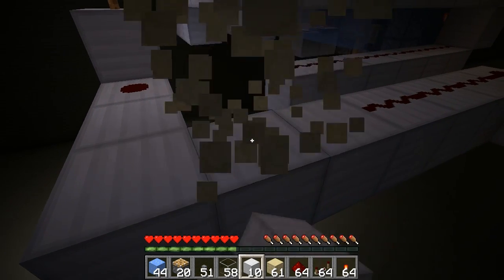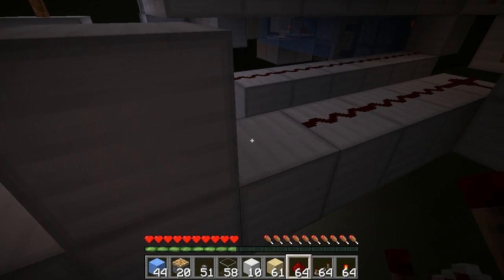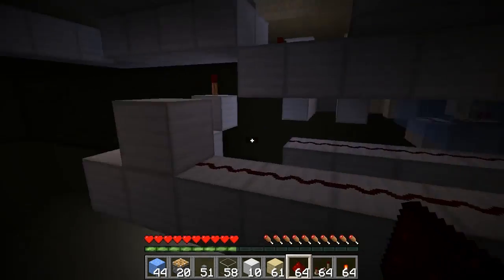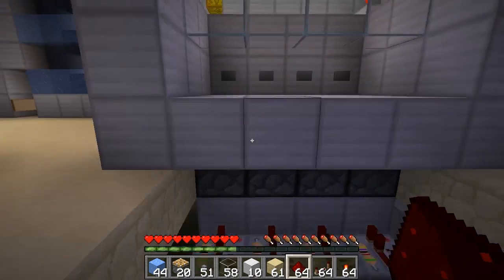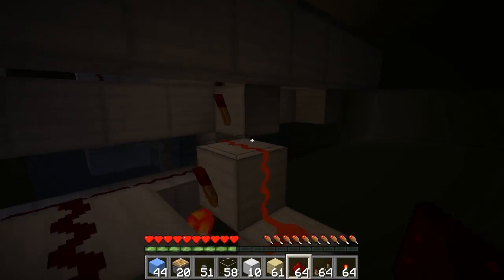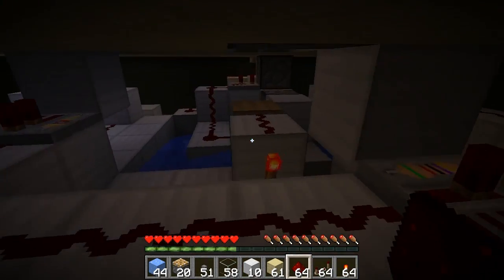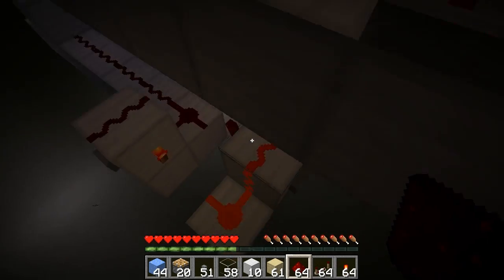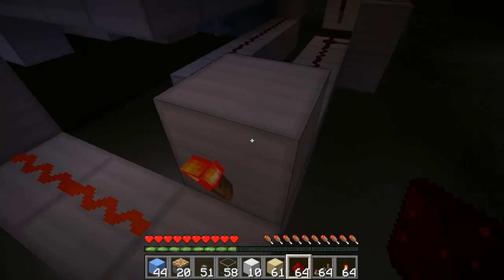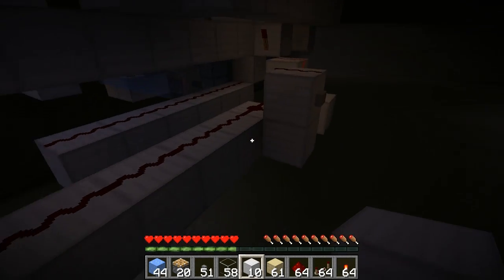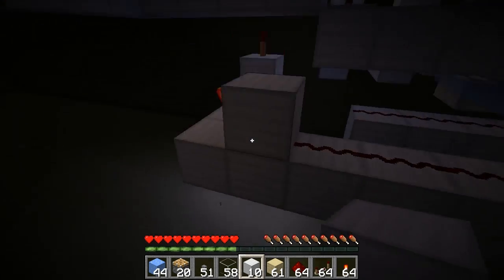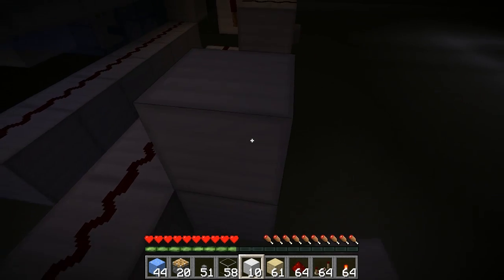So we'll need an inverter here, like so. So now that it's been powered, this gets depowered, which, well, gets set when 2 items fall through at the same time. This is also our reset line. So we'll need to tap into this at some stage later on.